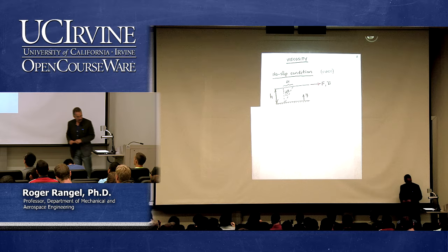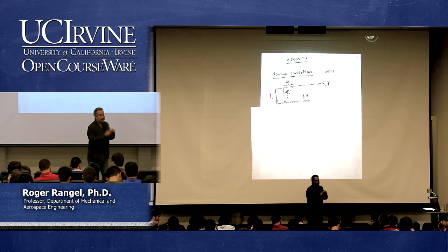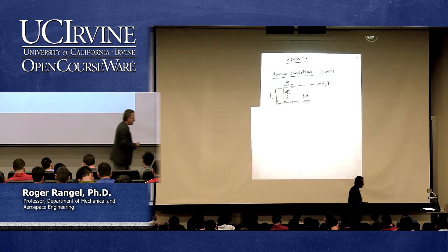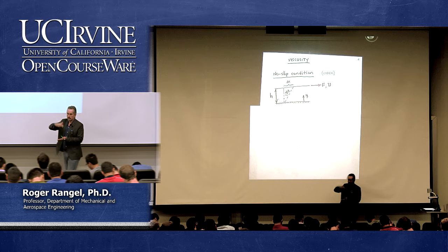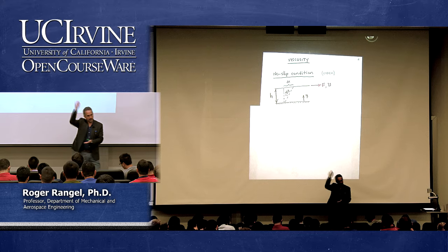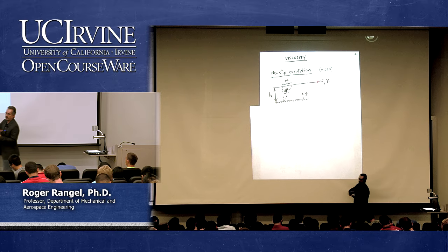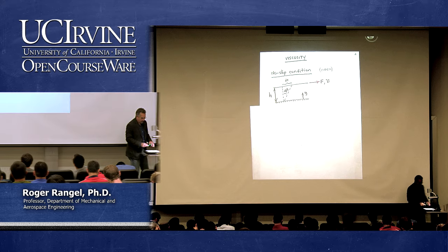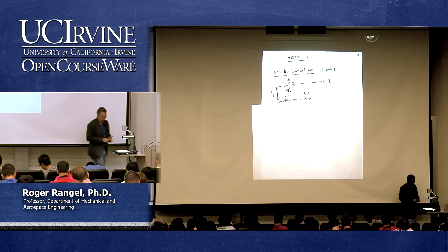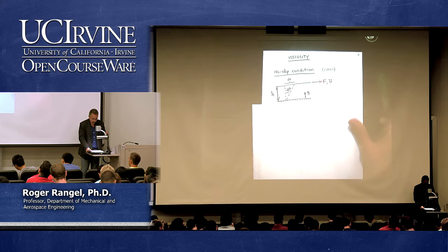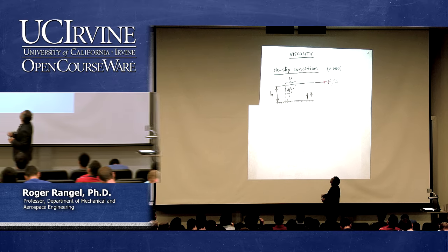This is a little different setup, but we're going to use this so-called no-slip condition to finally get a connection between viscosity and the fluid motion. Here is not exactly the same experiment that we saw in the video, because in the video we didn't see a top wall. There was a wall at the bottom, but nothing that we could see on the top. I'm going to add that top wall, like I did in the first diagram that I showed you when I was trying to show you the meaning of the shear stress acting on the fluid. So here the bottom wall is fixed, and I have a top wall that I'm going to move at will. By applying a force, which you can see here in red, I will be able to move that top plate with a constant velocity that I'm calling capital U.